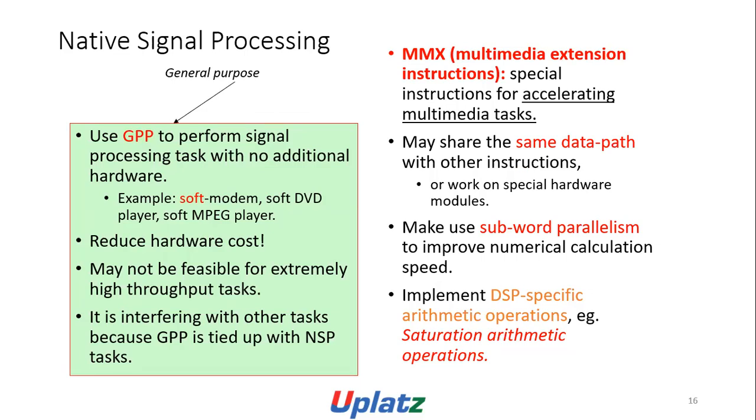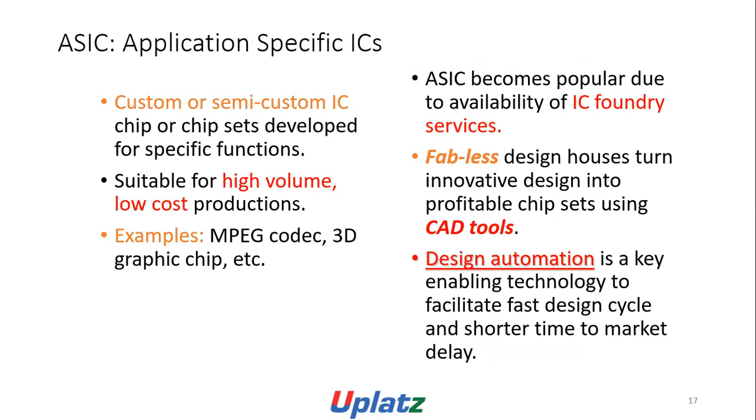MMX, multimedia extension instructions: special instructions for accessing multiple data, which may share the same data path with other instructions, or work on special hardware modules. They make use of subword parallelism to improve numerical calculation speed, and implement DSP specific arithmetic operations, for example saturation arithmetic operations. ASIC, the application specific ICs, are custom or semi-custom ICs, chipsets developed for specific functions, suitable for high volume, low cost production, for example MPEG codec, 3D graphic chip, etc.